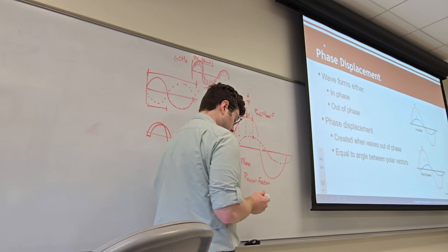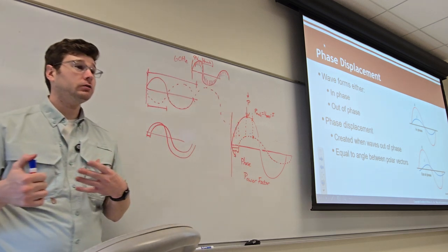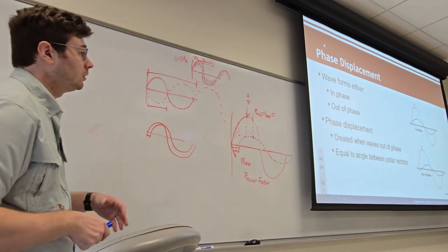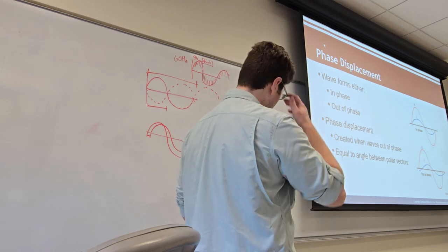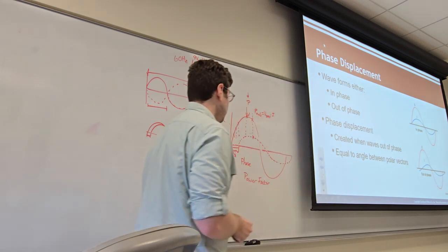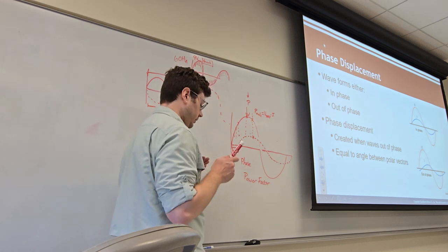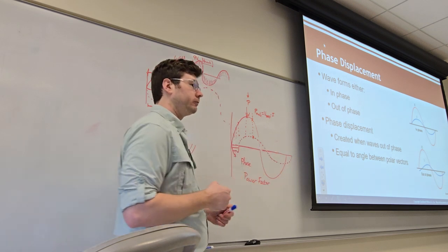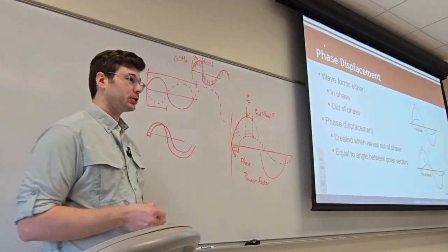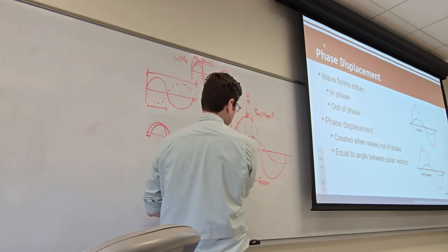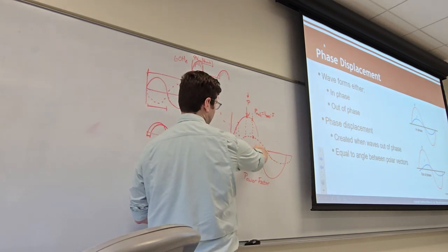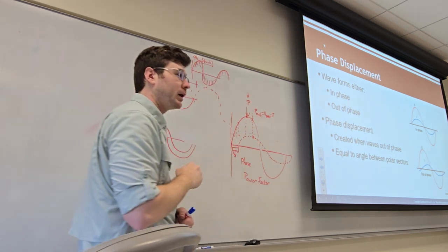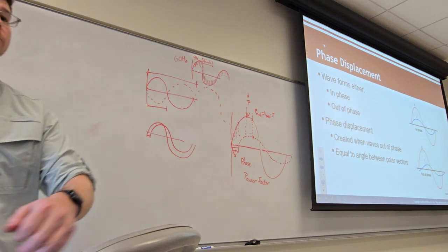The power factor comes into play, again, more in transmission. We're moving power from our power station or our generator to the thing that we're powering, but it nonetheless is really important to our system. We can actually add things to our system at the plant or at the generator to correct this power factor, literally called power factor correction. Okay, that literally shifts this waveform back over. It corrects the phase so the maximum aligns with the maximum and we get our maximum power back. So that is power factor and power factor correction.